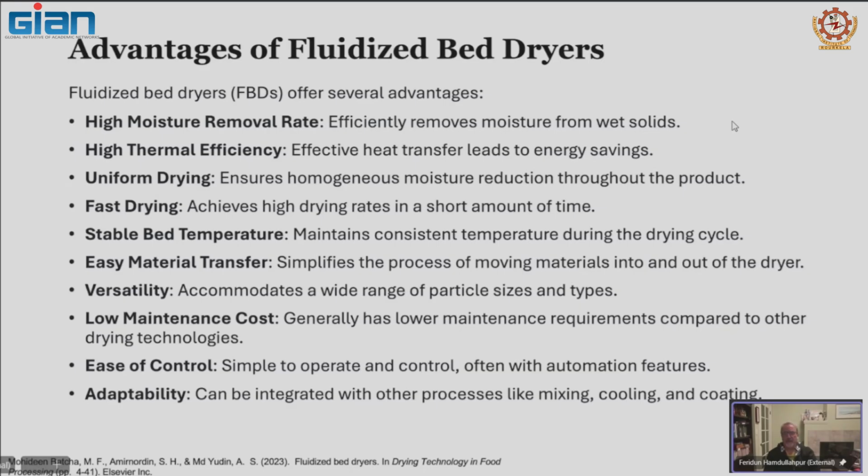Bed temperature is steady, stable, because of the large thermal mass you're creating in there. Material transfer is easy. The fluid bed makes it easier for us by having a fluid-like behavior, as we talked about, that it will obey all the hydrostatic laws. Versatility: you can dry wheat one day and the next day you can dry something else.